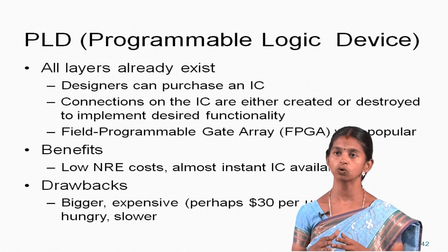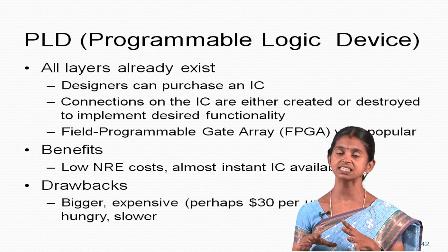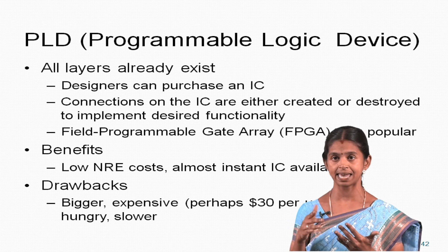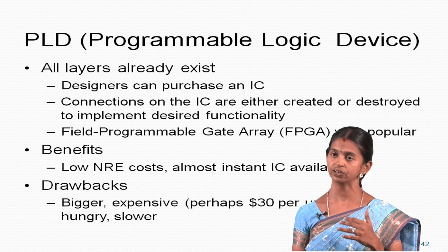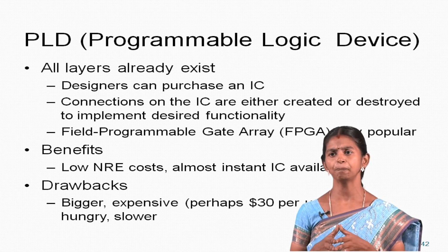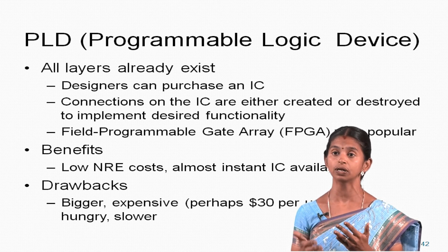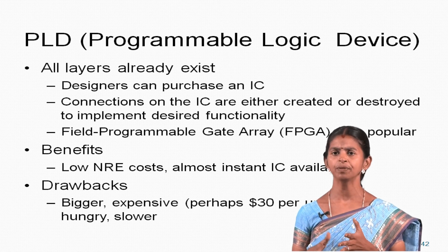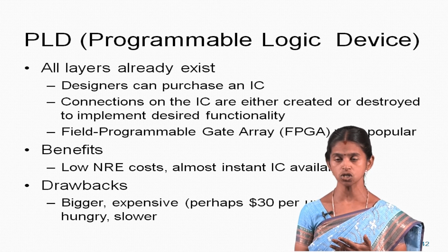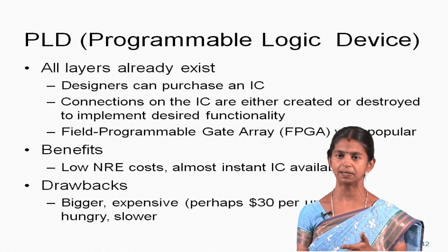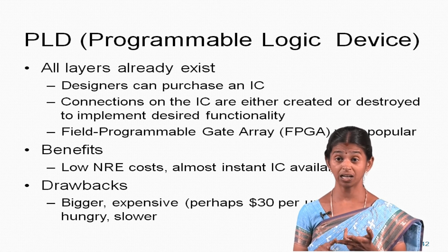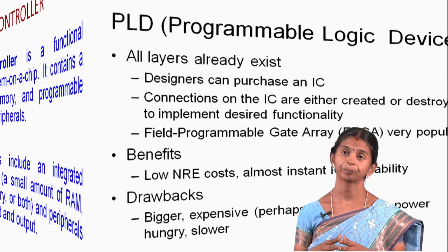PLD can be defined as programmable logic device. In this device, all layers already exist. Designers can purchase an IC. Connections on the IC are either created or destroyed to implement the desired functionality. FPGA can be defined as field programmable gate array, which is very popular. What are the benefits we gain from PLD? Low NRE cost, almost instant IC availability. Drawback: it is bigger in size, expensive, slower, power hungry.